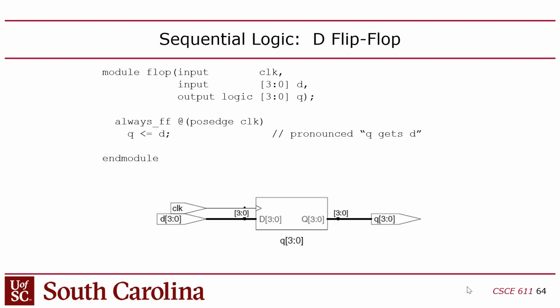So for example, when you do lab 4, we're going to have a branch instruction. If you take the branch, it has to automatically stall the next instruction. So you execute the branch. If it's taken, you have to flush out the next instruction that'll be executing in the next clock cycle. Well, how do you do that? You just use this. You have a stall signal that's generated combinationally in the control unit called stall fetch, and you assign that to stall execute in this statement.